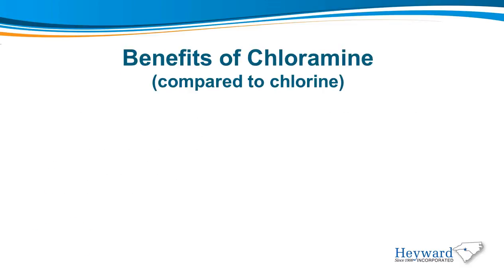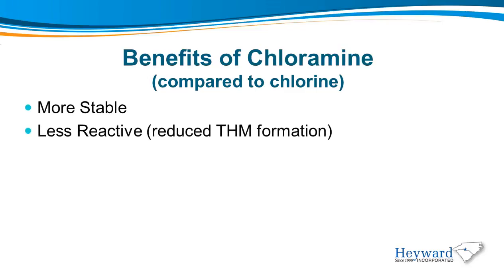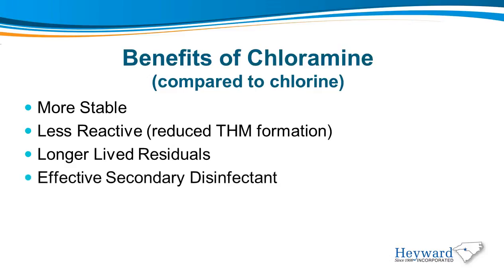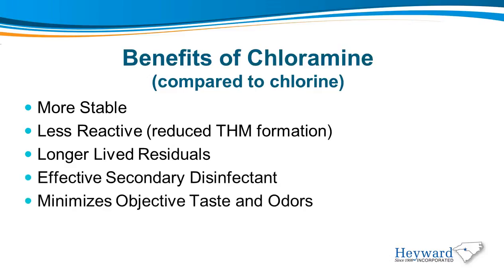There are benefits of chloramine when compared to free chlorine. For instance, it's a more stable chemical. It's less reactive, thus reducing the formation of trihalomethanes. It has longer-lived residuals in reservoirs and distribution systems. It's an effective secondary disinfectant, and it minimizes objectionable taste and odors.